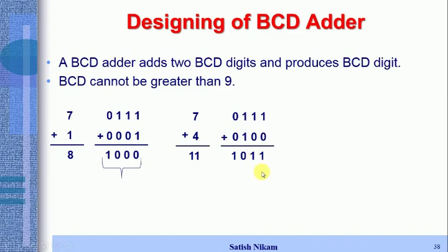So how do we convert it into BCD? By simply adding 6. We add 6 and we get the result 0001 as a lower nibble, and this is the 1 which we got. We can add 3 zeros here. So we have a valid BCD number. This is 1 and this is 1. This is the result 11 which we got here.